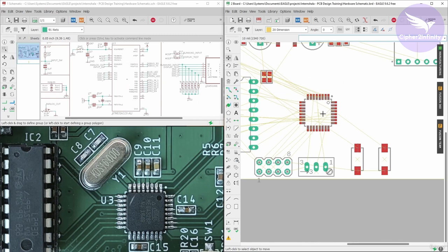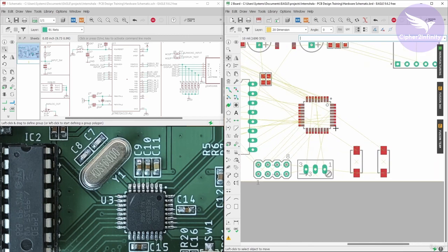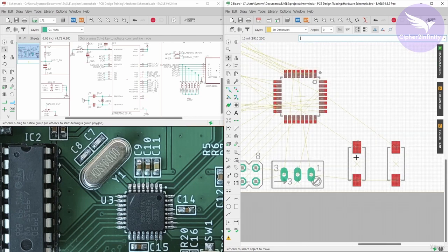This is a very common method, and most layout design engineers make changes in the schematic while creating the layout. But obviously they take the permission of the schematic design engineer. If some other person has created the schematic, then the layout engineer informs the team that this particular component is placed here, and that the pins on this side of the controller are more suitable for the user input switch.